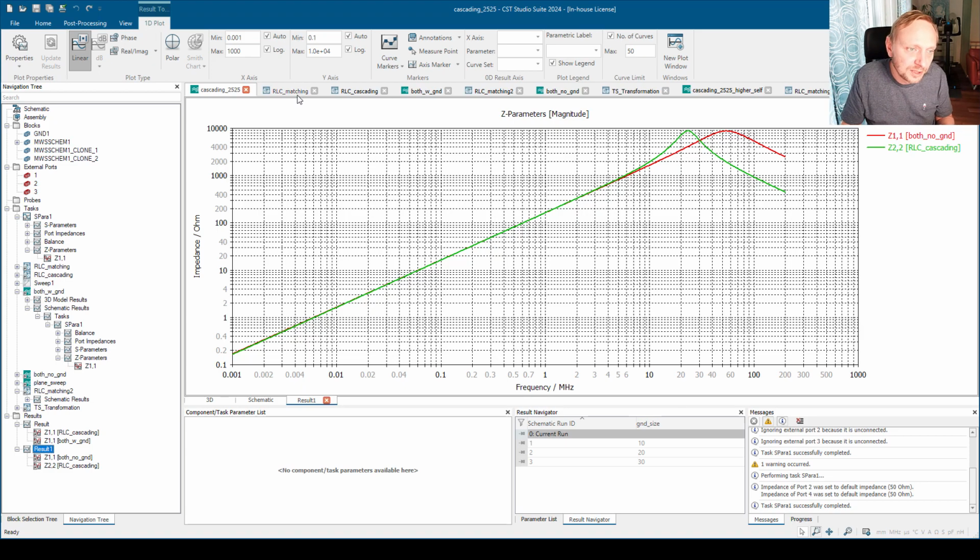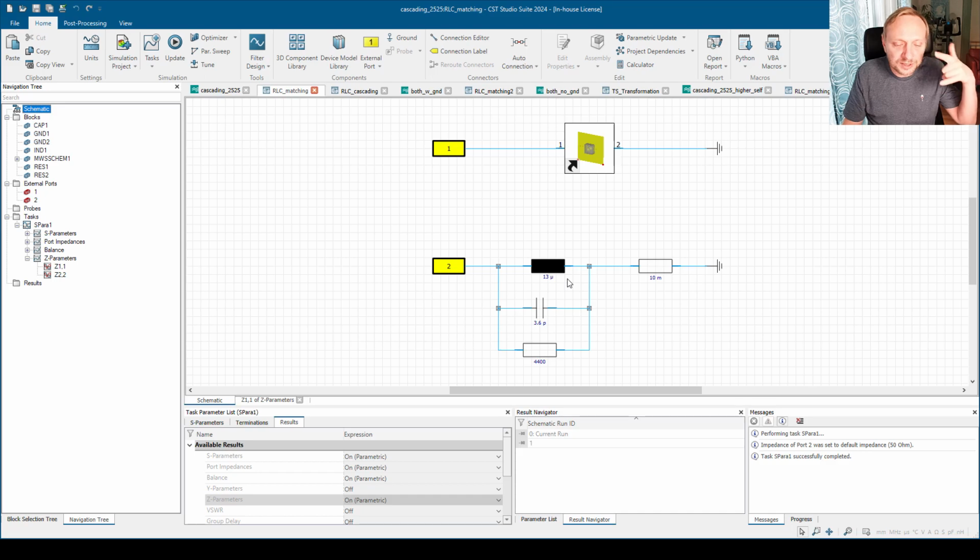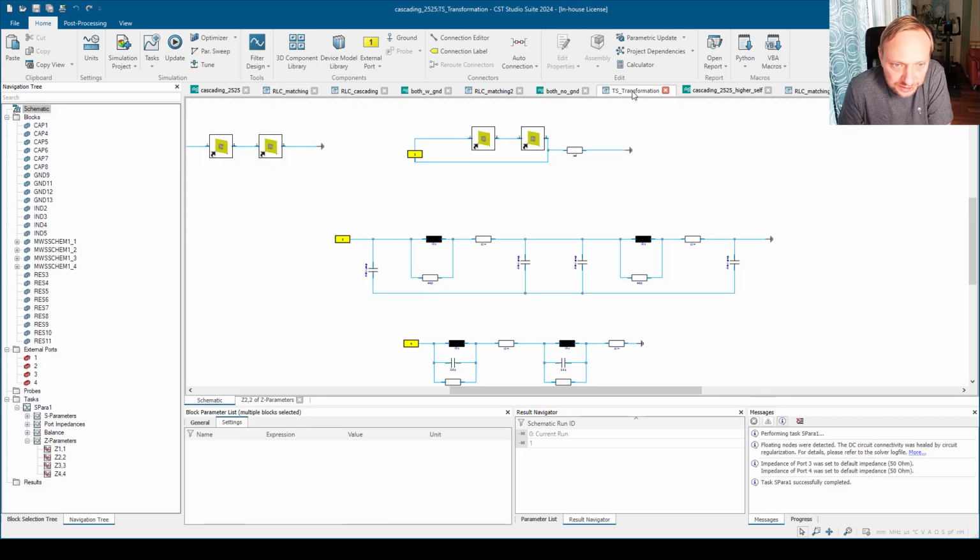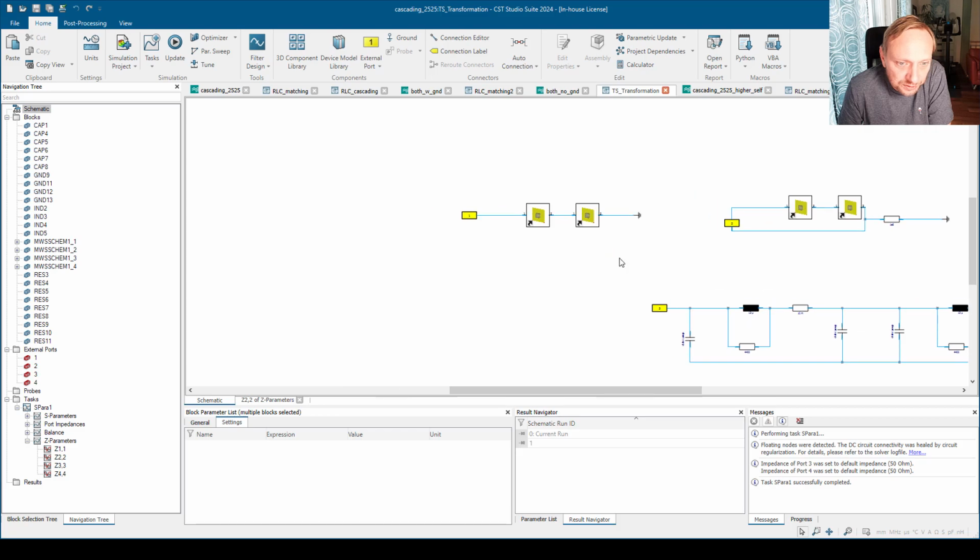So simply saying, at this point, the equivalent circuit I have chosen for my inductor is just not the right one. It just matches the impedance, and on a standalone, just one inductor, you don't see the difference, but it's still not the right circuit. And now we can do a few more fancy things.